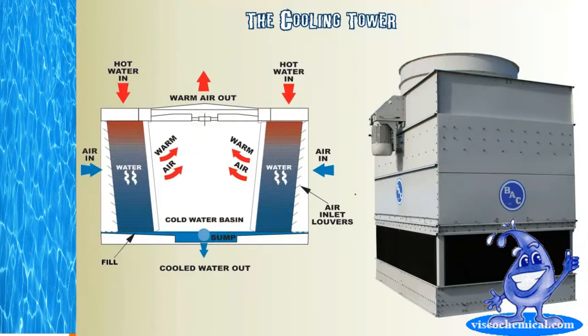Not too difficult. A lot of the control strategies that deal with cooling towers is when you have multiple cooling towers side by side, and either you use them as a staging where you have a cooling tower 1, 2, and a 3, so as it gets warmer you call on another tower, another tower, another tower. Or in the case of just having multiple towers, and it's dedicated for when you have one chiller, you run one tower. When you have two chillers, you run two towers. These are different strategies that you can have, as well as if there's one tower with multiple fans, so you might have two fans on the cell. This is a cooling tower cell.